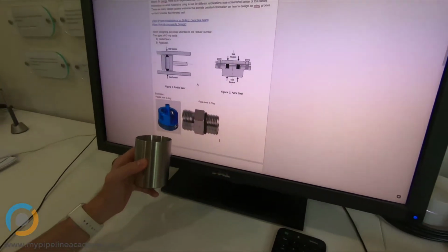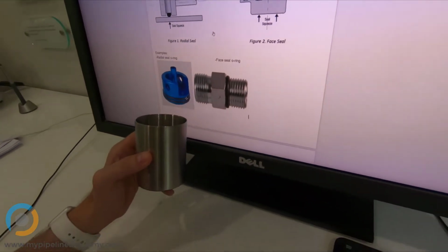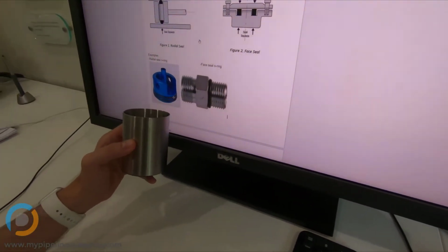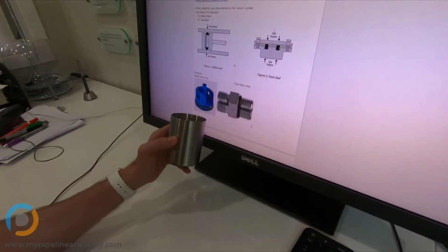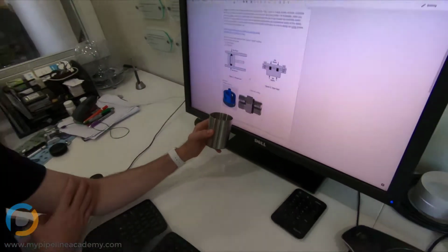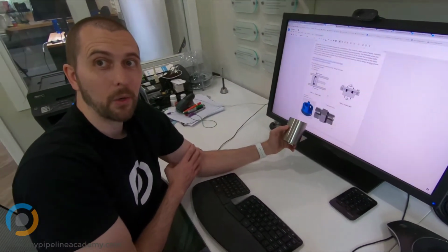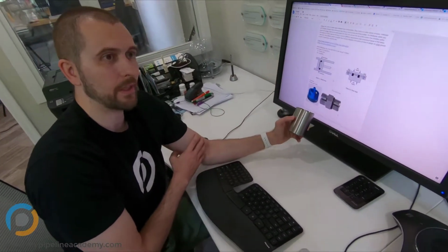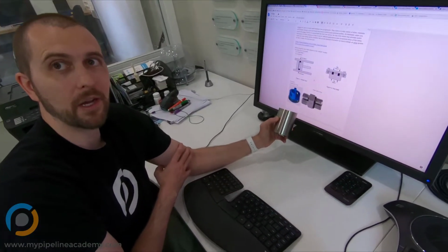Yeah, could be. So when we're a mechanical designer, does it really matter what we call them? They're really just O-rings used for different purposes. Right? Yeah. The distinction between a face seal and a radial seal is not in the geometry of the O-ring or the shape of the O-ring. It's in the application. It's how that O-ring is placed in your geometry.